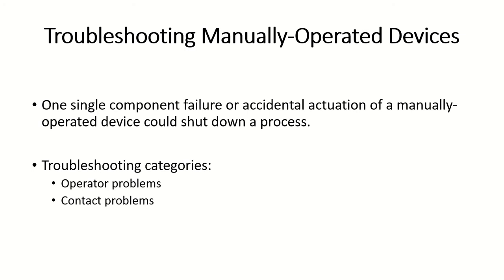Also, if you disconnect the wrong wire, or you pull the wrong switch out, this could potentially shut down a plant. So really make sure that you're paying attention to your control drawings and that you're confident that you're making the right moves.